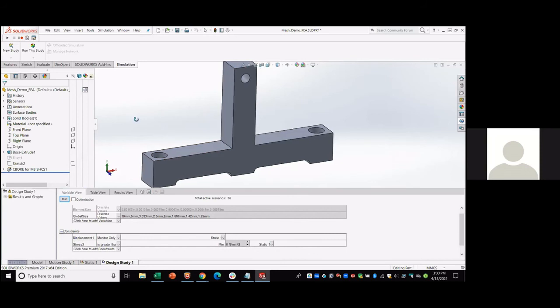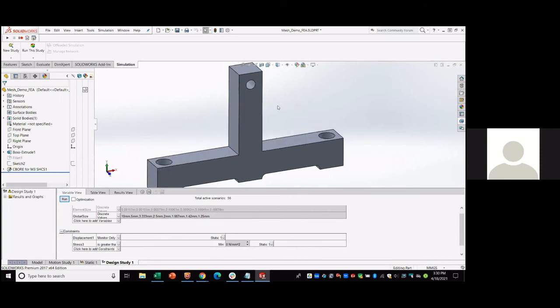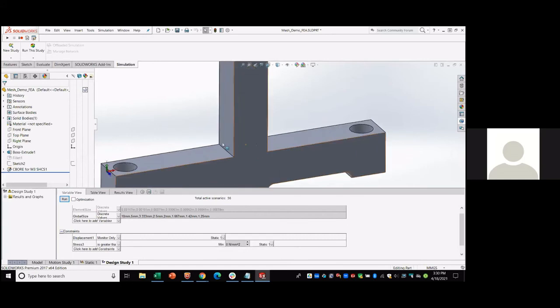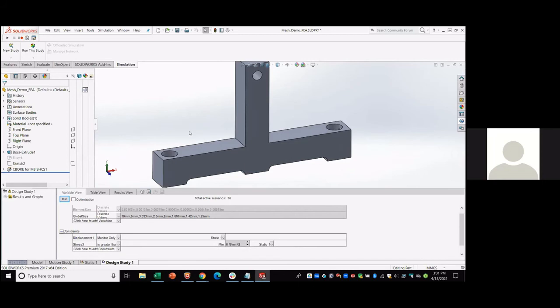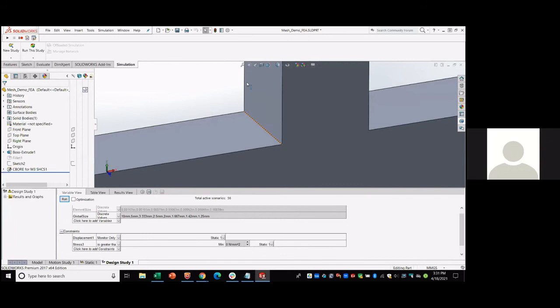Okay. This is something that you may find you end up having to resolve with hand calculations, because what's going to happen here is as we refine the mesh size, because this is a sharp corner, a perfect 90-degree angle. And actually, this is true for any sharp angle in any model that you run.